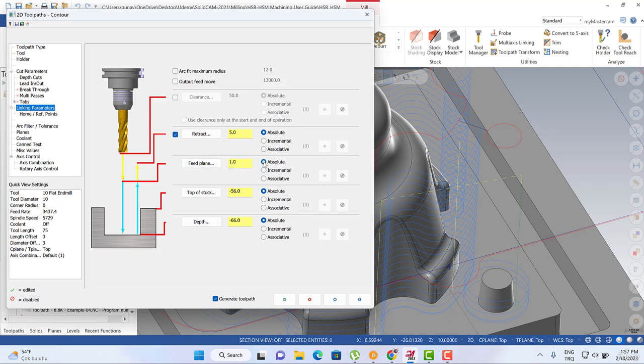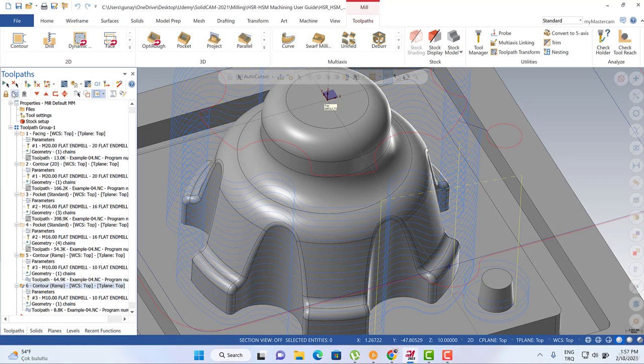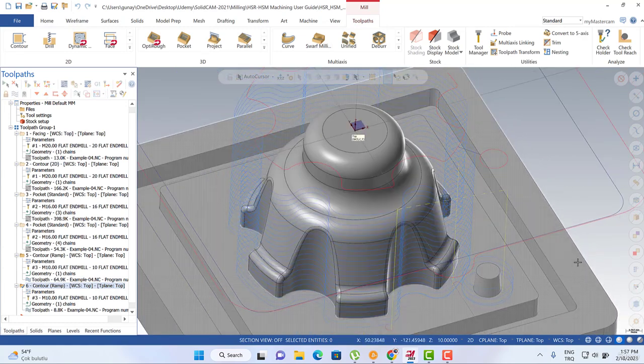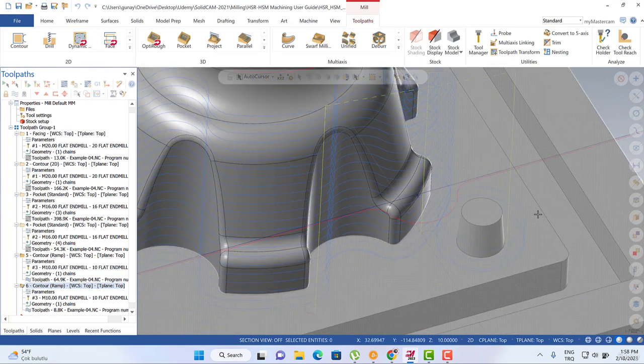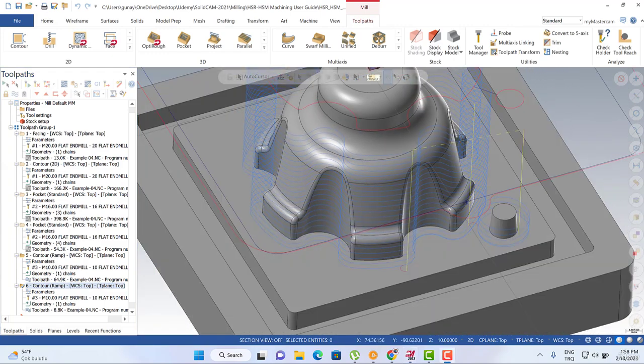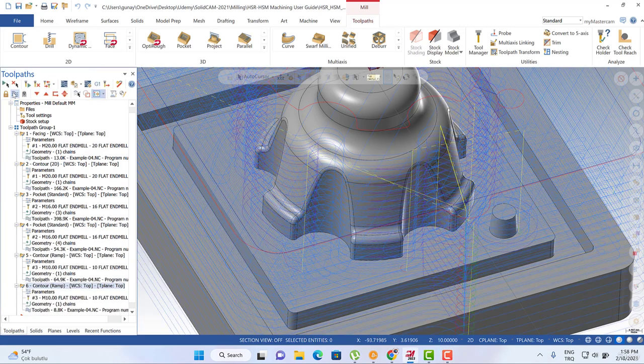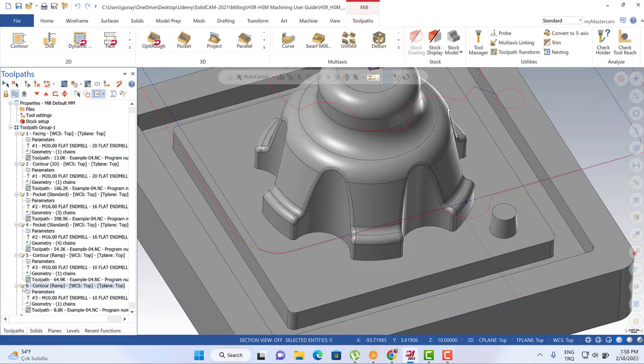Or we can also turn to absolute and Mastercam absolute position. We also know what our top of stock is. And then we just need to turn back here and make that 0.15 as absolute. So after that, we're going to see that kind of solution. We're going to move with the rapid movement at this point, and then after that we can repeat our cycling process. So that's quite important. That part is quite an effective way, I think.